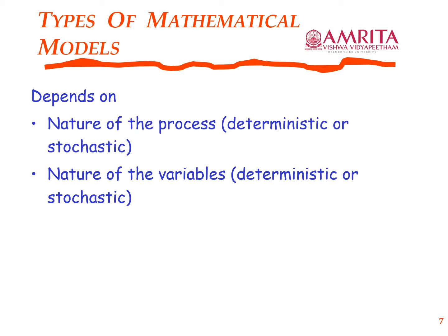Therefore that is captured by a stochastic variable which you define to be the residence time of that particular fluid particle, and then you look at the residence time distribution of all the particles that you collect at the exit.